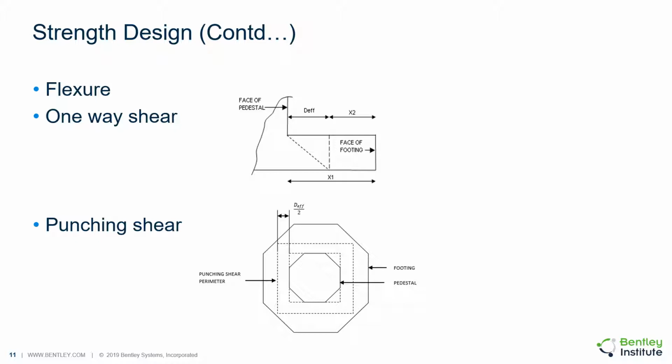The software checks that the footing is thick enough to allow for enough embedment of the pedestal dowels. It also checks that the footing is wide enough to accommodate the development length of bars from the face of the pedestal.